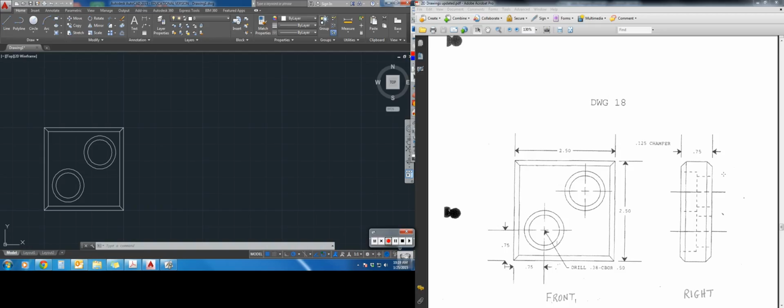When I draw the right side, everything on the right drawing must line up with the same object in the front view. So when I'm looking at this, the tops need to be at the same height. One way you can do this is I'm going to draw a line, and let me turn my snap back on. I just want them to be 2 inches apart, so I'm just going to draw a perspective line going out to the right 2 inches. I'm going to do that on both the top and the bottom. And later I'm going to delete those lines because I don't want them there.